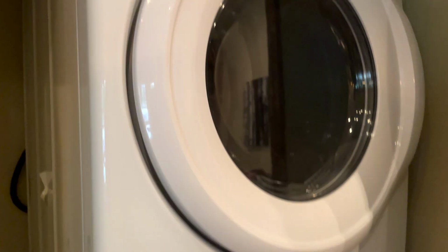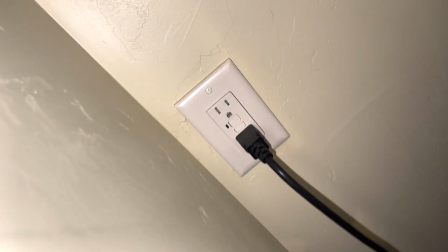That's enough room. There's no water catch pan underneath the clothes washer. I like to see a water catch pan. And there's the dryer. We know it's electric from the electrical panel, and the washer's plugged in, and it's a GFCI. Every receptacle in the laundry room has to be GFCI protected. I get to see the discharge pipe there, hot and cold water supply lines.